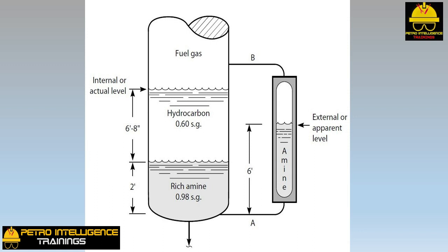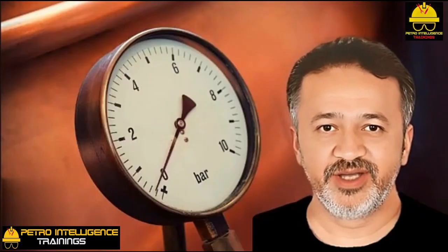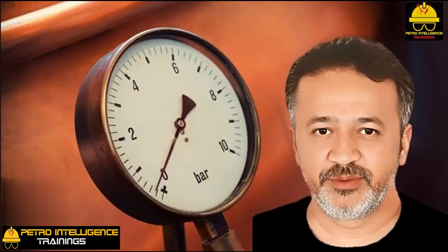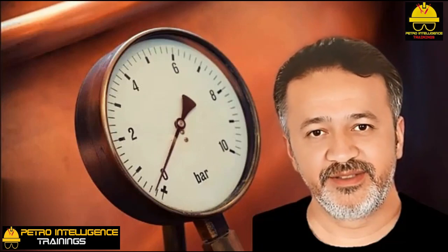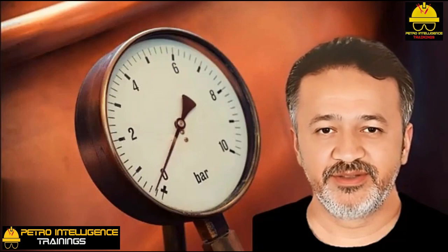the gauge glass level. If you conclude that we could use the gauge glass level to actually calculate the level inside the tower, you are quite wrong. To perform the preceding calculation, one would have to assume the ratio of the phases. But this is an assumption equivalent to assuming the answer.